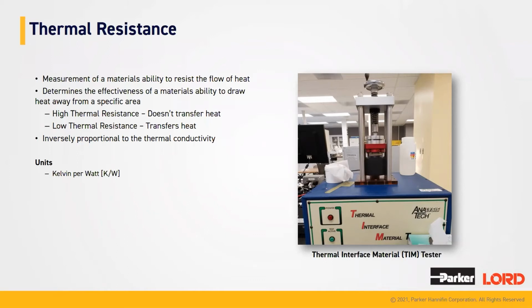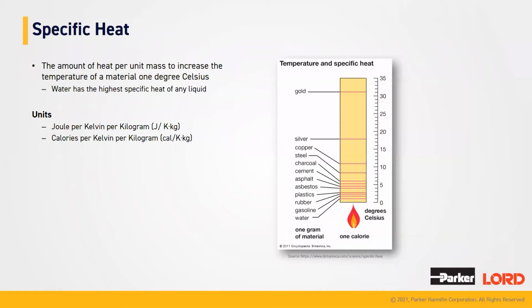And so the thermal resistance, it's worth noting that it is inversely proportional to the thermal conductivity. And so on the right here, you can see an image of our equipment that we use to test the thermal resistance. It is the thermal interface material tester, more affectionately known as the TIM tester. And the units for thermal resistance are Kelvin per watt.